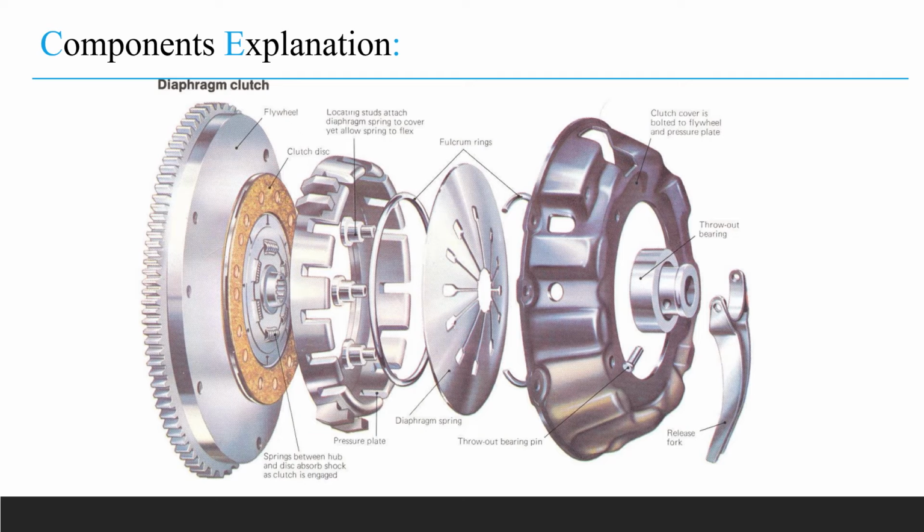When the release bearing is pushed into the spring, the inner portion of the spring is moved in the direction of the disc clutch, whereas the other portion of the spring moves oppositely. Now, the clutch is disengaged as the pressure disc is mounted in a flexible manner to the casing. So the clutch disc can be locked between the flywheel and the pressure plate when the release bearing is released as it is pushed into the diaphragm spring. Through this whole process, the mechanical energy produced by the engine is transmitted to the gearbox, and the clutch release bearing is released, and the clutch disc is now engaged.